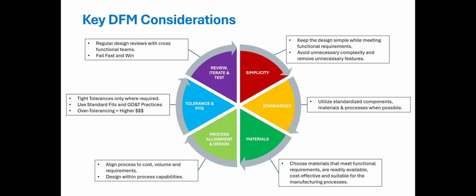Following that, you want to consider tolerance and fits. Going into more detail, you only want to apply tight tolerance as required, because the more tight tolerance you incorporate into the design, the more expensive and complicated it's going to get. That being said, when designing a part, you always try to use standard fits and GD&T practices, just to help simplify, as I mentioned earlier.